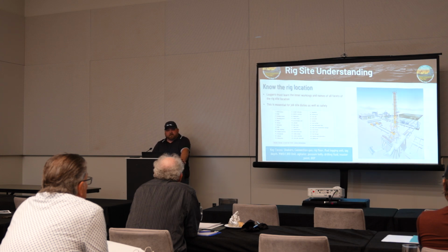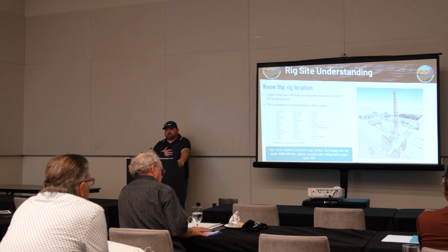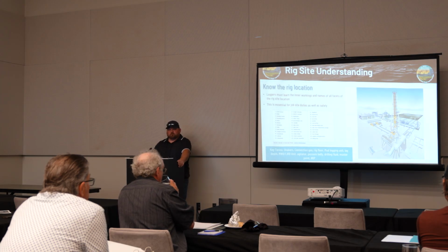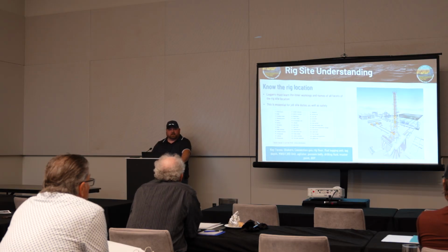Triplex, duplex, they both have different types of strokes and barrels per stroke, which goes into lag calculation, which I'll get into in a little bit. So knowing where those pieces of equipment are, what you're actually working with, even though it's not our equipment specifically, it's all stuff that as a mudlogger we really need to know to better perform our analysis and data collection.